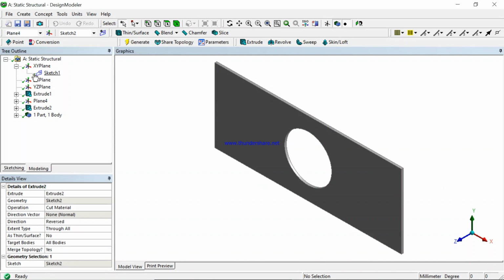We can continue to simulation, or you can simulate it as a full plate, but as long as the geometry you're dealing with is symmetrical, it's always advisable to use symmetry. Now, what is the importance of symmetry? Symmetry is going to help you in the first place, the runtime for your simulation, and your CPU time. So it's going to save you a lot of time by analyzing a single portion of this plate instead of running the whole plate. So in this tutorial, we are still going to learn how to apply that.